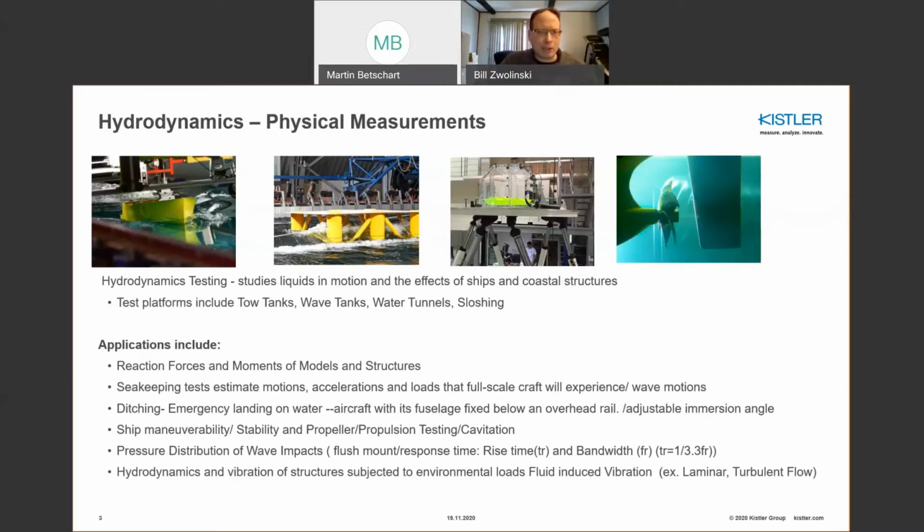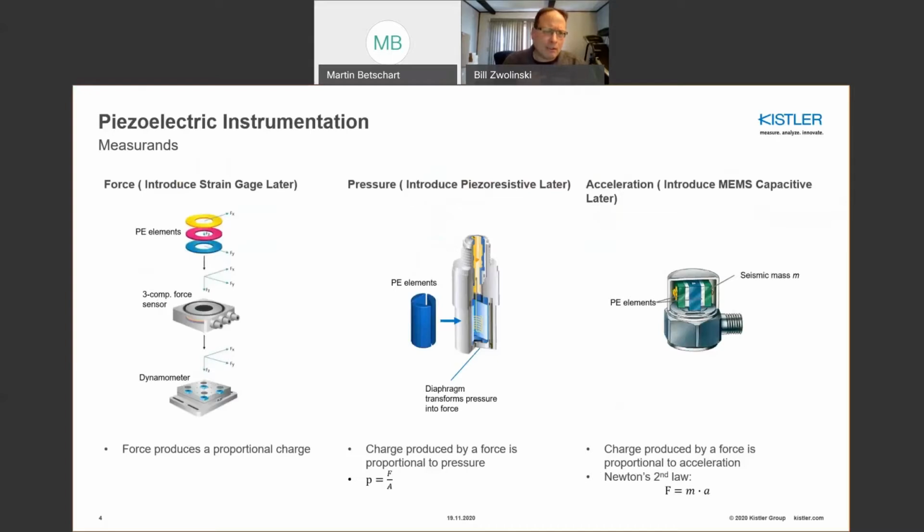So here we go. As far as the piezoelectric instrumentation goes, we're primarily using a quartz piezoelectric material, as you see in the force sensor slide on the first part. You have quartz machined for shear forces or compressive forces, tensile forces. This gets integrated into a sensor and then into a dynamometer.